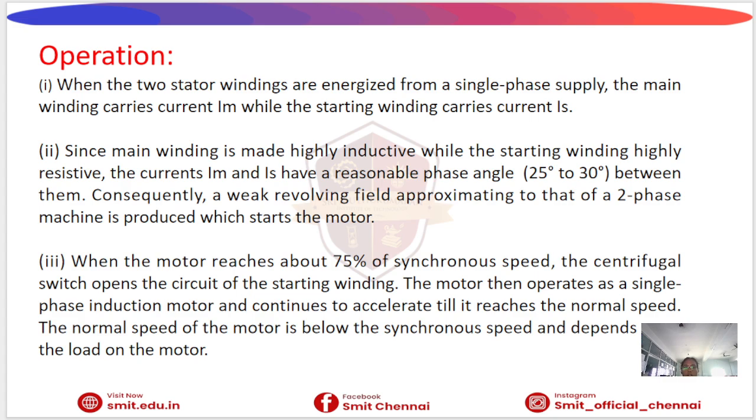Disconnection of starting winding. When the motor reaches about 75% of synchronous speed, the centrifugal switch disconnects the starting winding. After that, the motor continues to run as a single-phase induction motor. The starting winding is only for starting the motor.